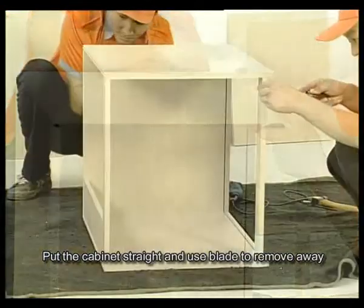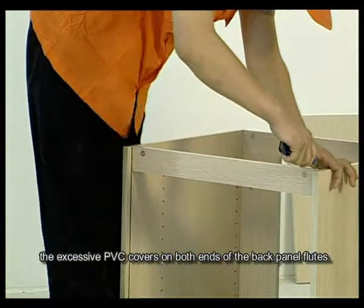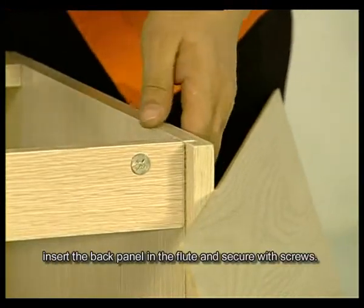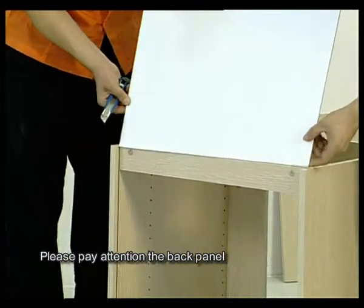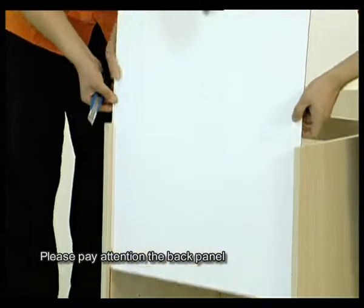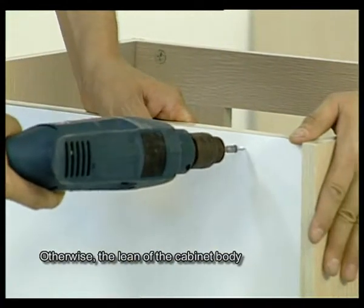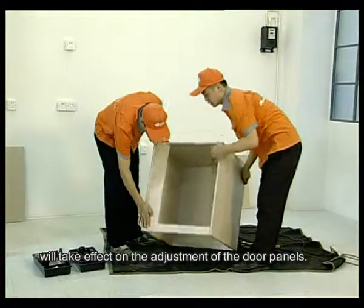Put the cabinet straight and use a blade to remove the excessive PVC covers on both ends of the back panel flutes. In the end, insert the back panel in the flute and secure with screws. Please pay attention, the back panel should go along well with the flute. Otherwise, the lean of the cabinet body will take effect on the adjustment of the door panels.